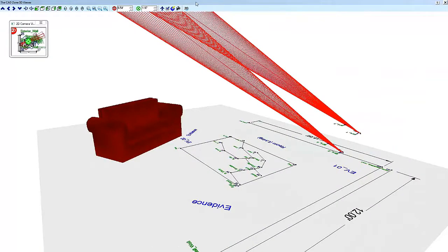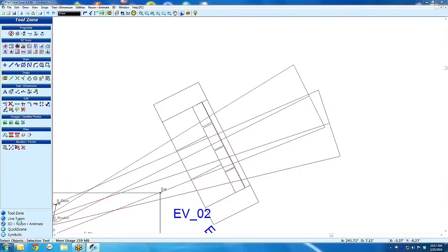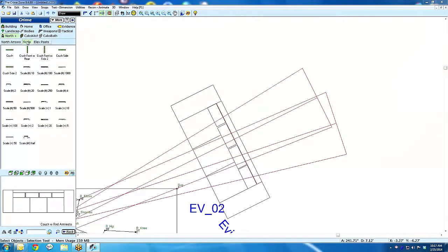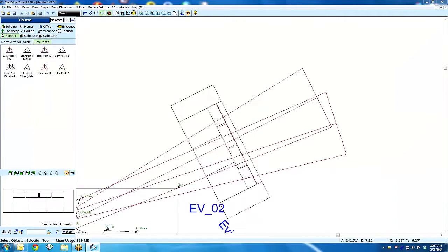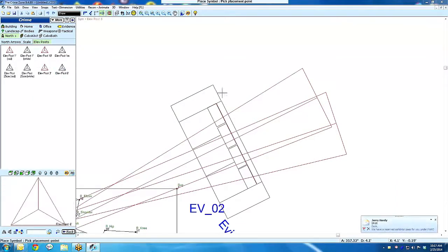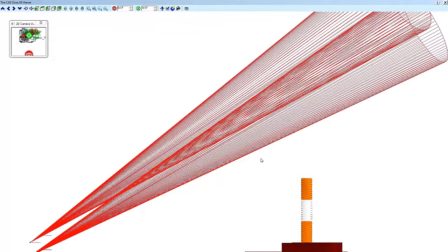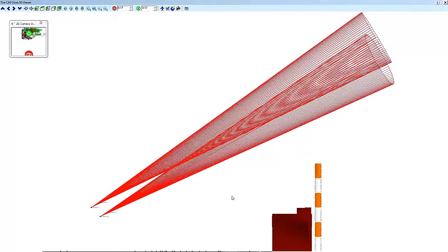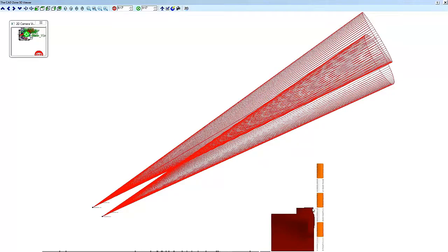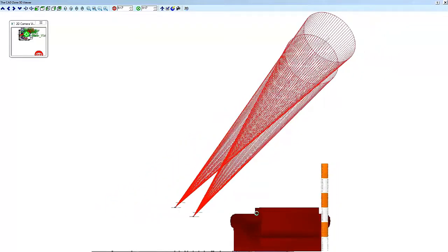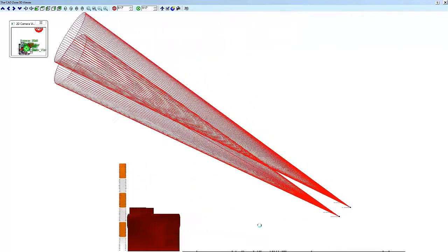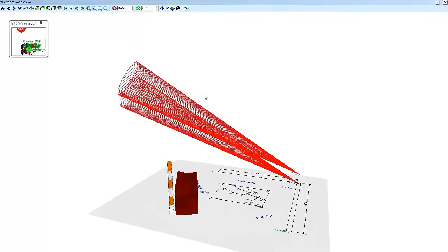But how do you know it's really 3 feet high? Well, the program told you it was, but we certainly could go into symbols, just go to the North Plus scale elevation posts, and let's grab a 6-foot post right here, and we'll put one right there, and then we'll go back into 3D. So the post is graduated by feet and divided into tenths of a foot. So if I do just a perfect side view like that, and then we just kind of turn around it, you can see 1, 2, 3 feet exactly. So you can verify anything you've done, or you might want to use it to see where you can stack these posts on each other or add more to it.